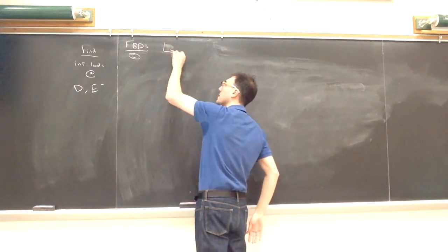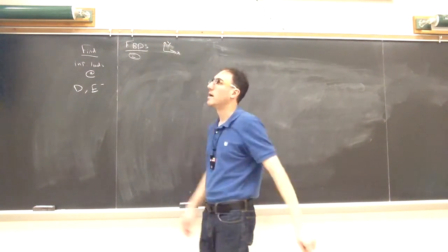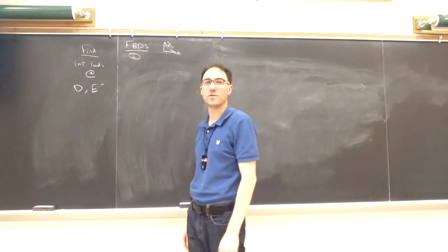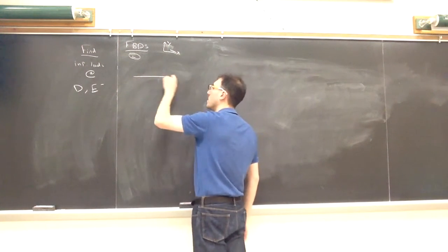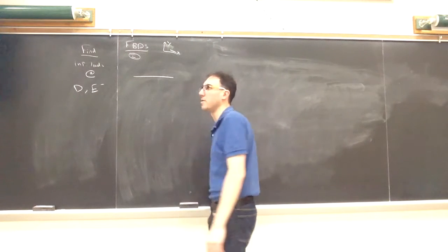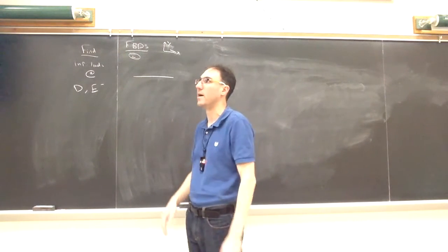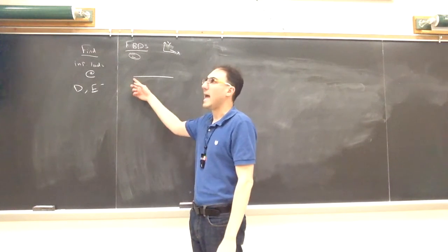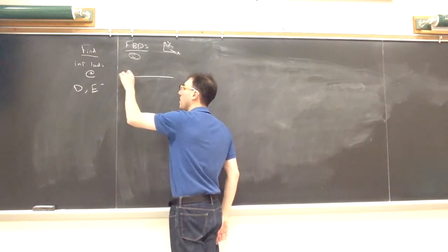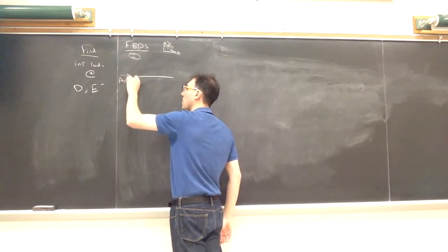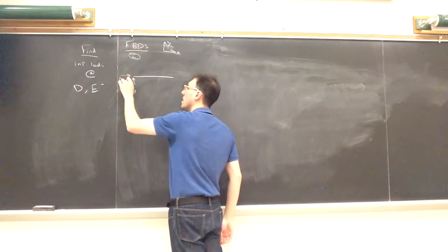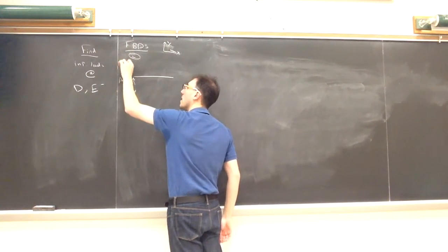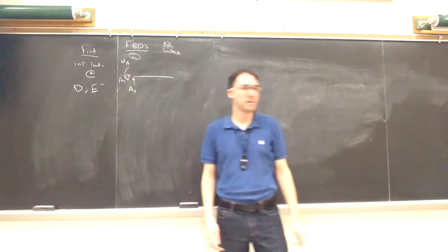So my first free body diagram, I'm going to take from A, the member that goes from A to B first, and model what's happening just to that piece of the member. At A, I have that built-in connection that I want to model. I have the Ax, the Ay, and an MA.